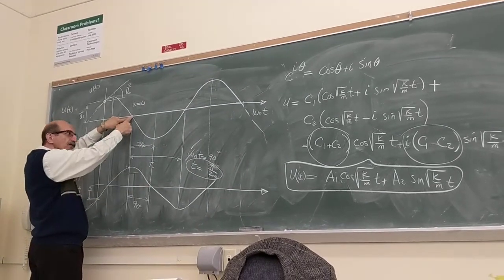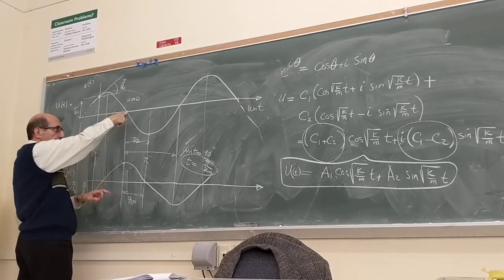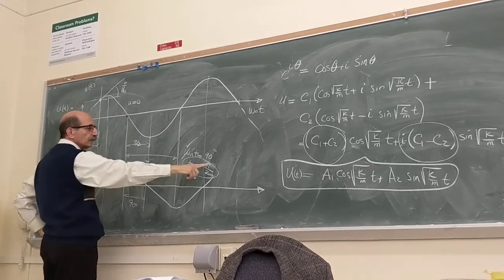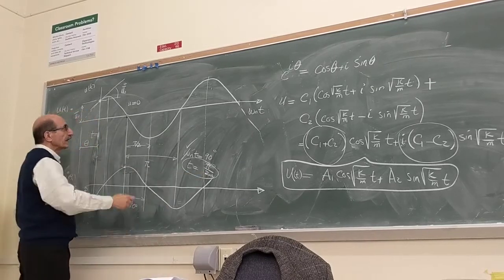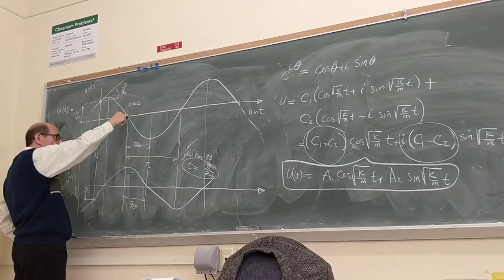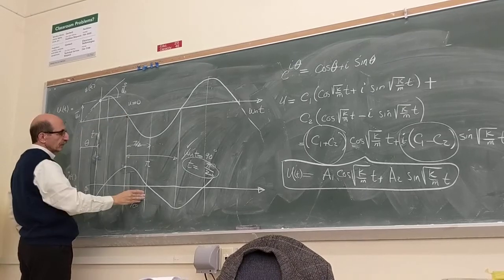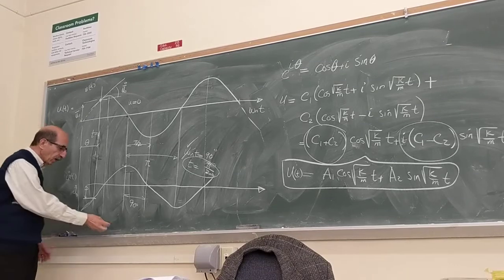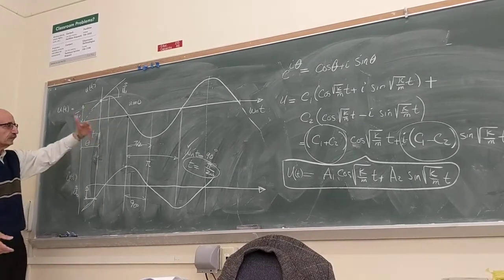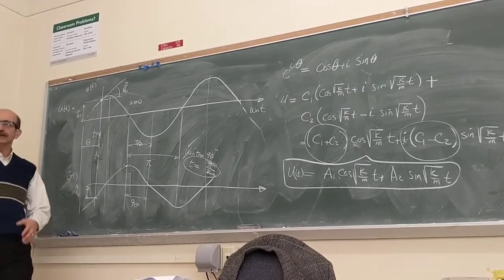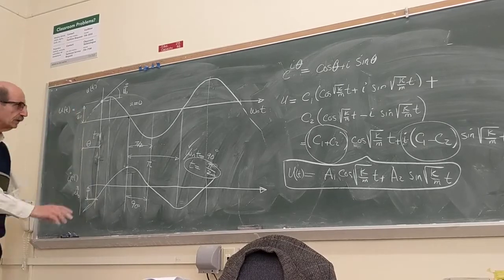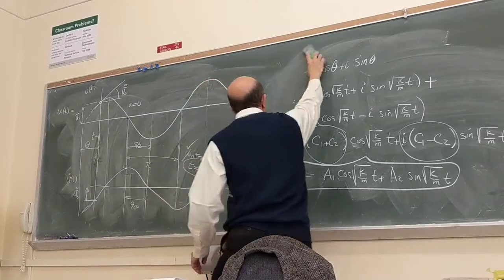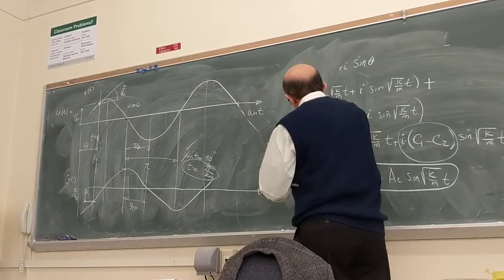So when the displacement is 0, velocity is maximum, but after a time of pi over 2 omega n after the displacement is 0, velocity goes to 0, right? So that means basically how the velocity and the displacement relate, and you can also plot the acceleration and relate these two and so on. We'll do that. You do all kinds of stuff in the lab to study signals and so on. But for the time being,